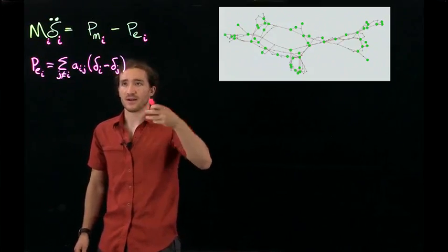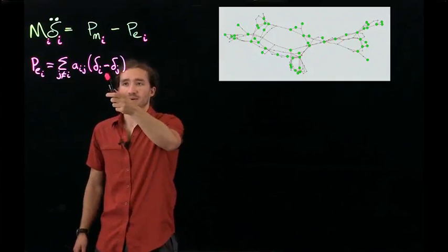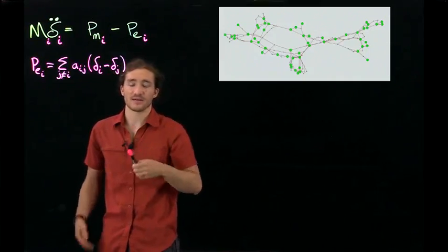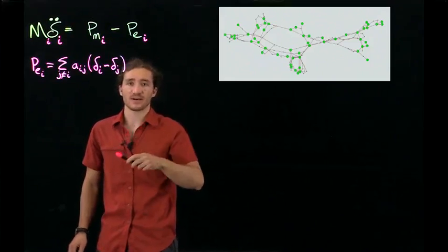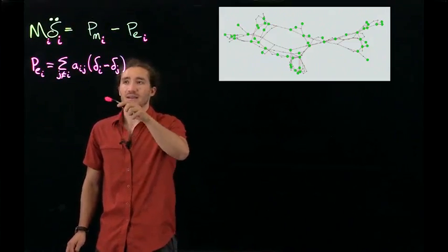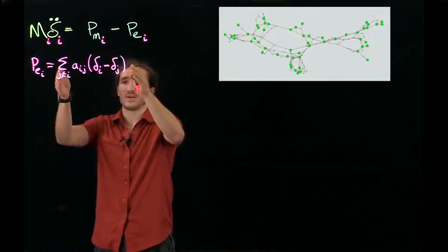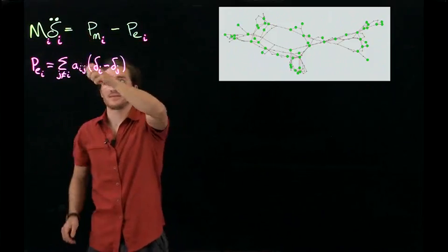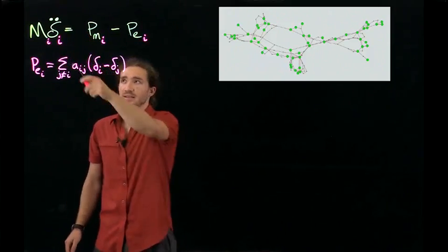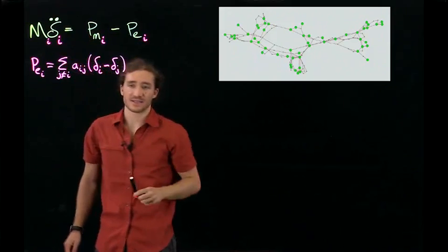Now, if we look at the other scenario, where let's say that rotor I has less value than all the other generators, then we use the term lagging. So if generator I is lagging, this term will be negative, which makes this term positive, which makes this whole term positive, which means that rotor I is actually accelerating now.